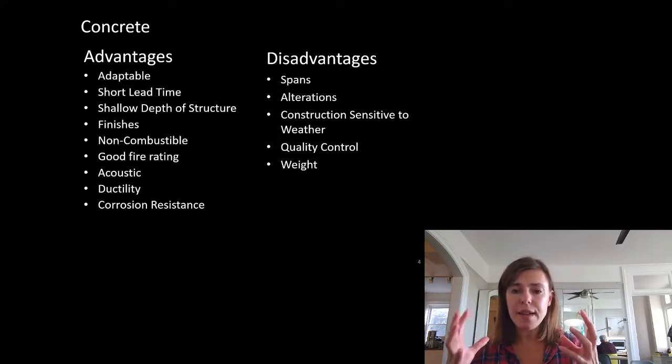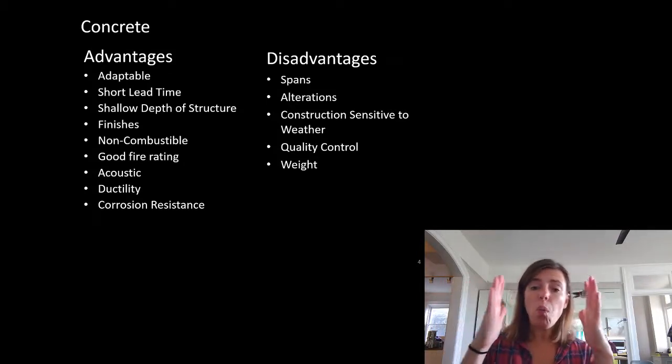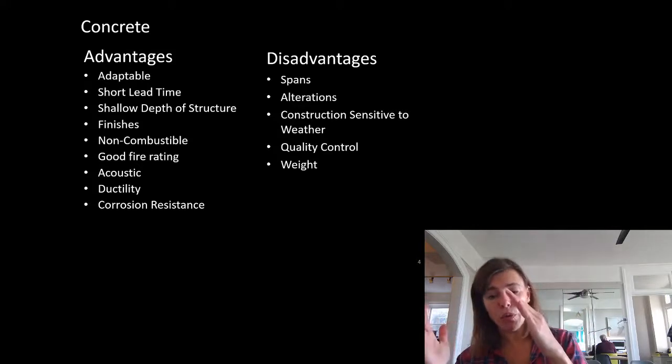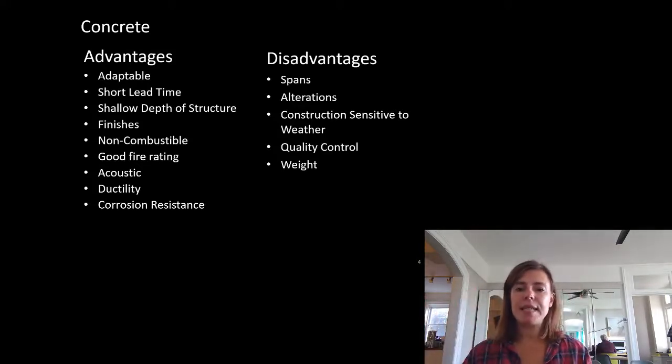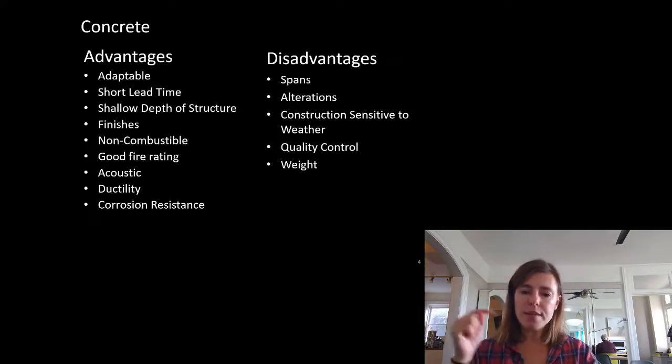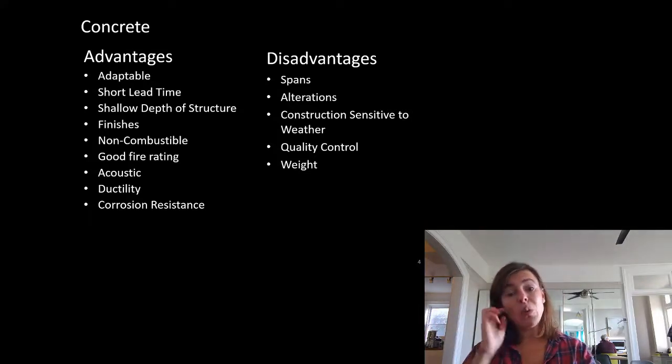We like ductile things because they absorb energy, or dissipate energy, if you want to think of it that way. So in high seismic zones, we want our building to move so that we don't have to resist as heavy forces, because those forces are going into moving the building, not breaking the building. So we like ductility, and if we put steel inside our concrete, we can get a very ductile building.